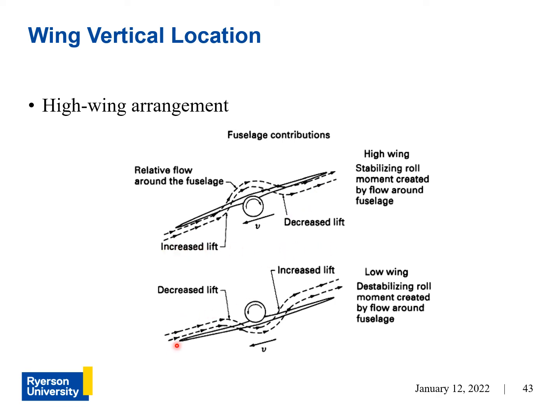Now, a low wing arrangement with no dihedral will have the opposite effect. So that's why it's typical to have a dihedral for low wing arrangements.